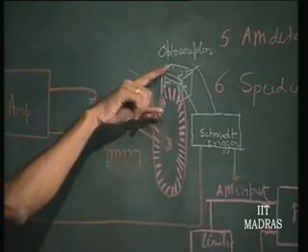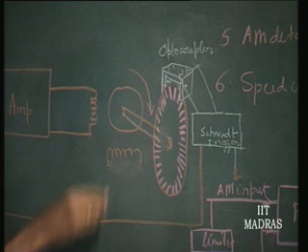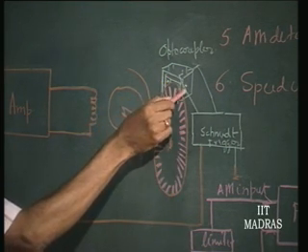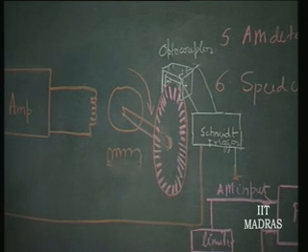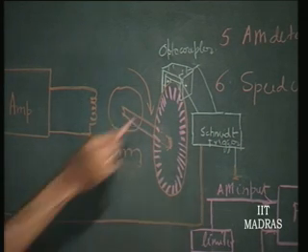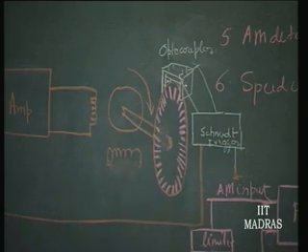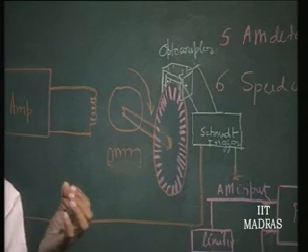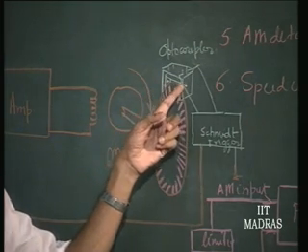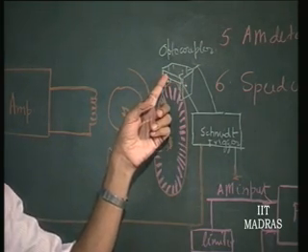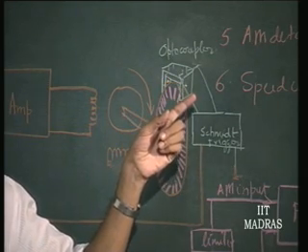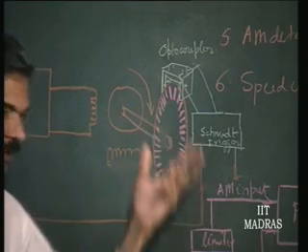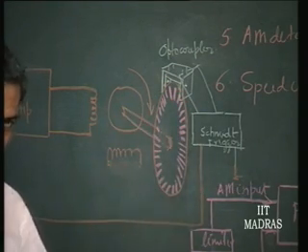Then you put what is called an optocoupler such that the light that is being emitted by the LED here is collected exactly by the light detector on the other side. These optocouplers are already available in this form with a slot. They can go right into the slot. The advantage is they have the hole here, so that the light emitted just exactly falls on the light detector. That is what is called an optocoupler. This kind of optocoupler suitable for this optical tacho generator is readily available in the market.